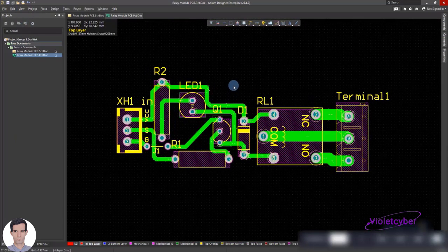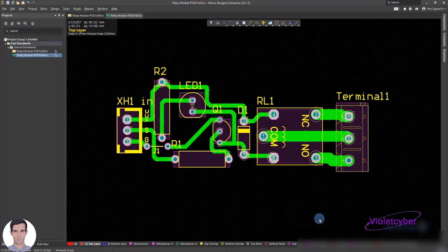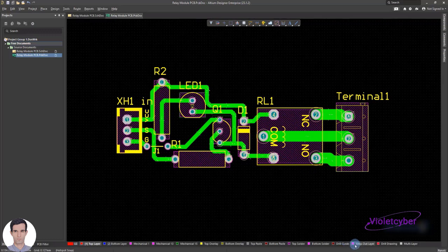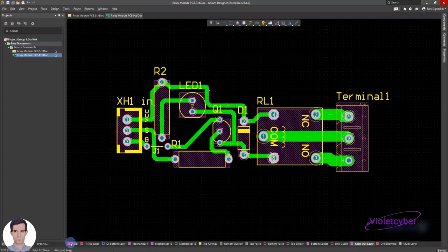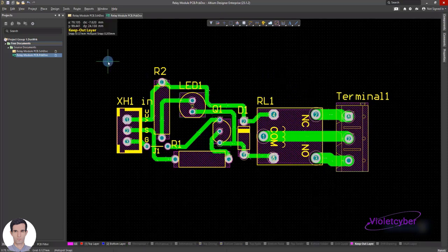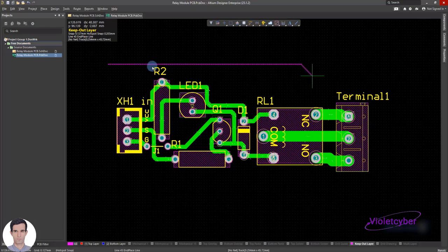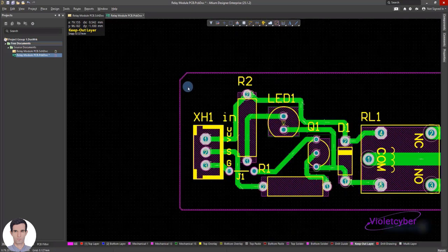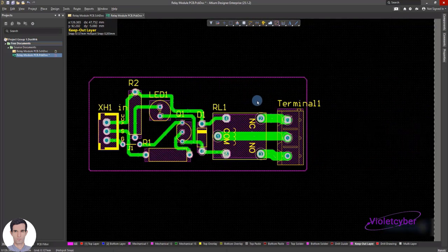If you remember from the previous session, we learned how to make cuts on our circuit. Here we come to the program because we are doing the board outline. We select the keep out layer. We double-click the method. We select it here. See where we double-click this document. It is selected. And then we go and select the line, and we go and draw a line around our circuit. So these lines are connected like this. We will make this side as well. This way, it will be connected. You will see this space.